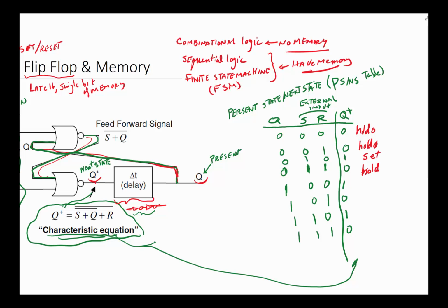Normally, this doesn't make sense under the terms we are using here because it is set and clear. You can't have set and reset both be 1. But anyway, it's there and it's 0. Because this equation gives us 0, we're going to write a 0. And then we got 1 staying 1, Q and Q plus, so that's called a hold 1. And then the next one is reset, fine. Then it makes sense, set is 0, reset is 1. So it's going to be that. And then this one is hold 1. And this last one is, once again, because set and reset are both 1, normally not allowed, but it's there and we're going to get a 0. But that is also going to be just a reset, right?